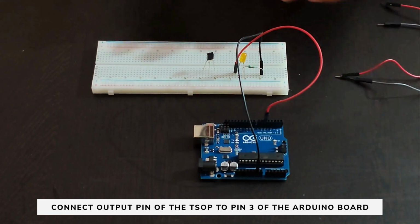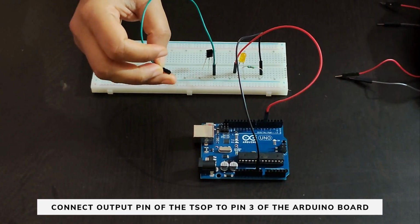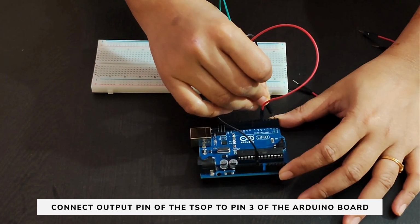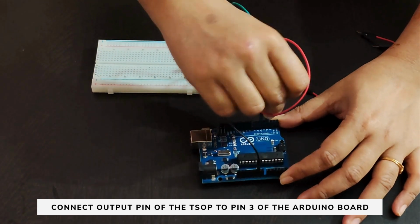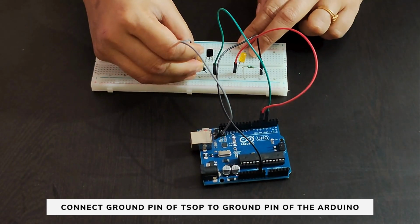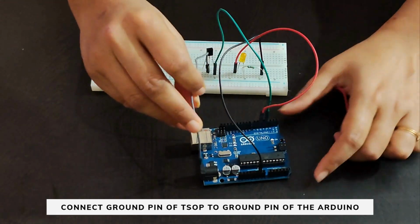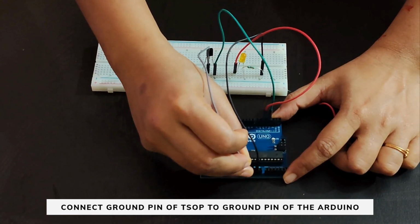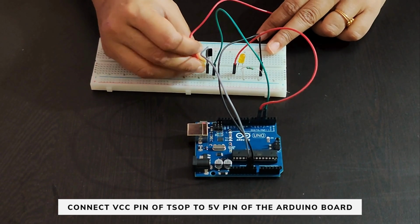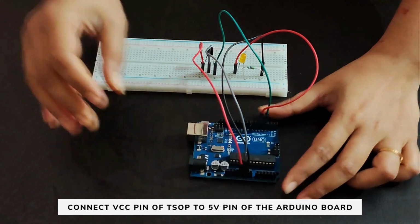We will connect the output pin of the IR receiver to pin number 3 of the Arduino. The ground pin to the ground pin of the Arduino and the VCC pin to the 5-volt pin of the Arduino.